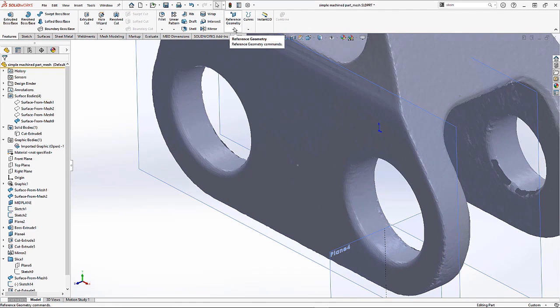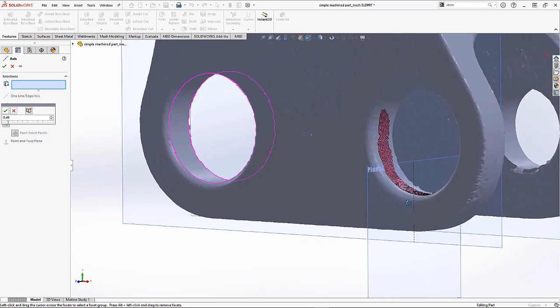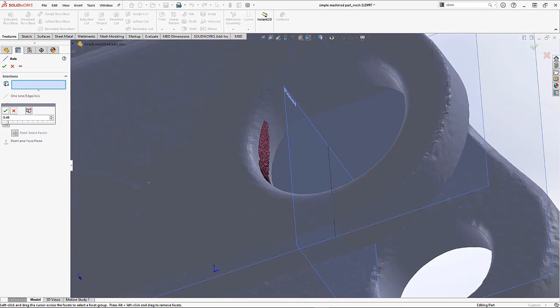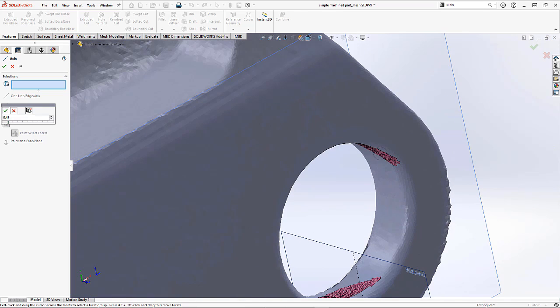Let's take a look at another option. We're going to create an axis that goes through a cylinder, but with the cylinder option we have a Paint Selected Facets option now. If we select some of these and paint down and around this hole, we can rotate it around and paint all the way around 360, and we're generating an average of these different facets around this hole.